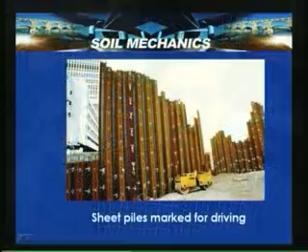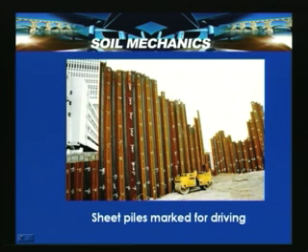So in this slide, a typical sheet pile wall is shown where these are marked for driving into the soil. Sometimes these are also used for protecting temporary excavations, like what you are seeing here, a high-rise building. So to prevent any collapse of the soil in front of these, particularly these sheet pile walls are driven into the ground to retain the soil behind this particular section.